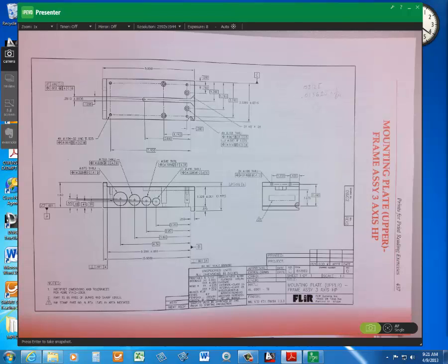That's still pretty tight. 14/1000, that's 1/1000th of an inch less than a 64th of an inch. And counterbores are kind of run on 64ths. Okay? All right? So the critical thing here is the position of the hole.